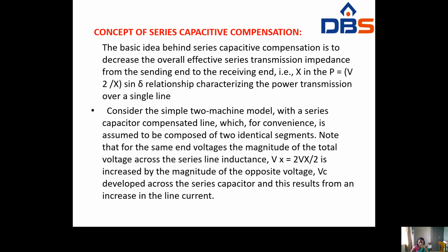The basic idea behind series capacitive compensation is to decrease the overall effective series transmission impedance from the sending end to the receiving end, such that in P equal to V squared by X into sine delta, the relationship characterizes the power transmission over a single line.